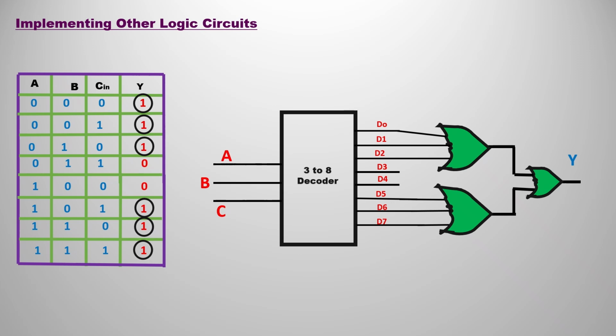In the market we only have 2 input OR gates or 3 input OR gates, and a 6 input OR gate is rarely available. So we proceed with 2 and 3 input OR gates, connecting them directly. We can also connect the 6 at a time with an OR gate, but remember, we have to proceed with what is available in the market.